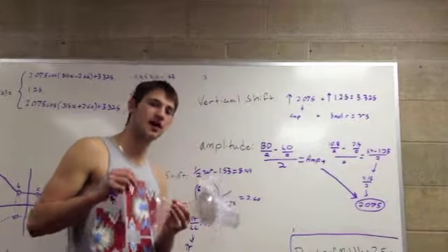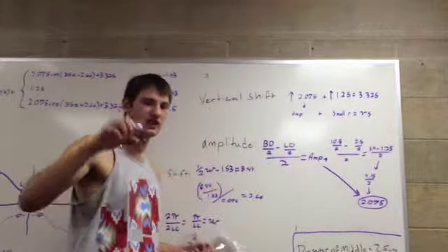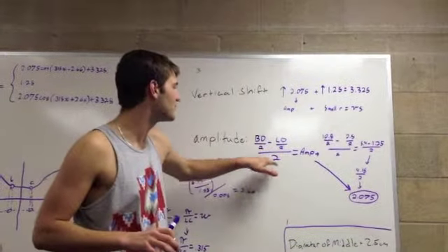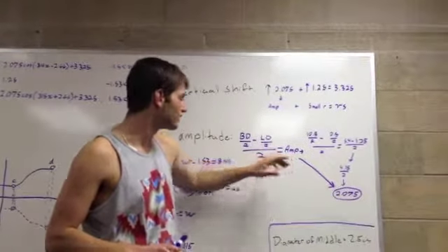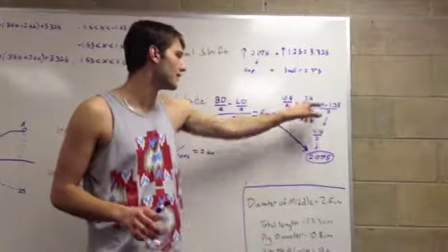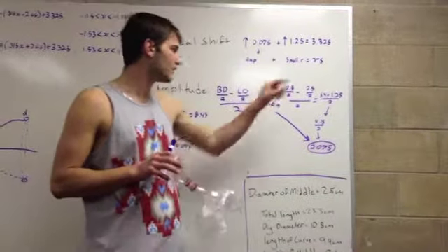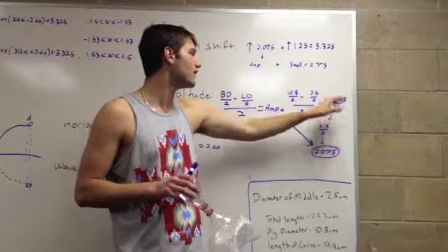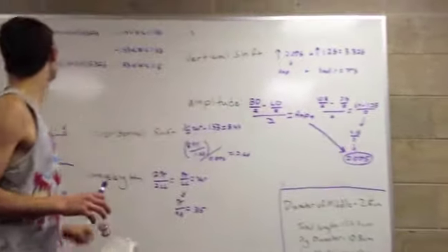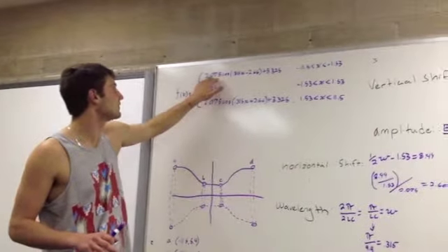Now, because when you take a cosine wave you split it down the middle, the amplitude is only half of the distance from the trough to the peak, so you divide it once again by 2, and that's how you get the amplitude. So using 10.8 as the big diameter, divide that by 2 for the radius. 2.5 is the diameter of the small curve, divide that by 2 for the radius, you get 1.25. Divide that all out again, you get 2.075. You come back over here and you put that out front because this is the space for the amplitude on the graph.